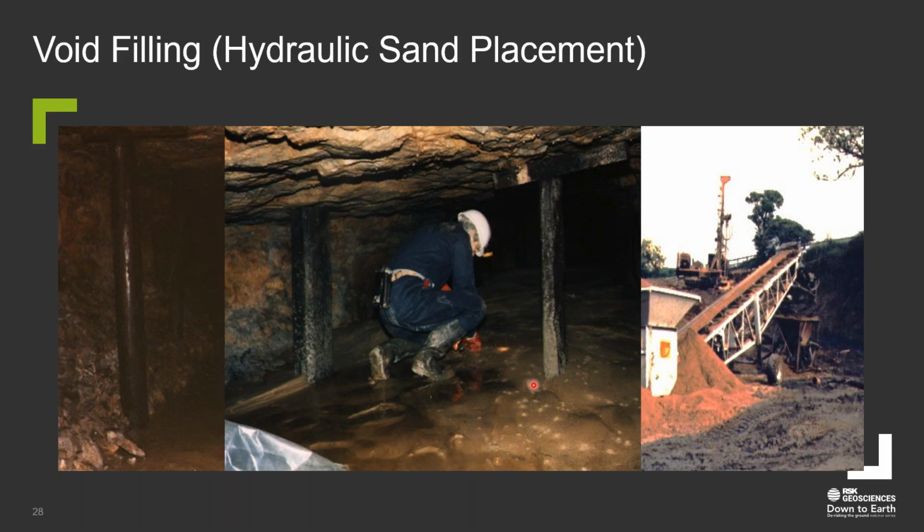That's me in there sampling the sand. That's a half built cavity now. We've got it to go within about 50mm, 100mm of the roof from a very limited number of injection points. And then we fill that upper void space with PFA cement grout.